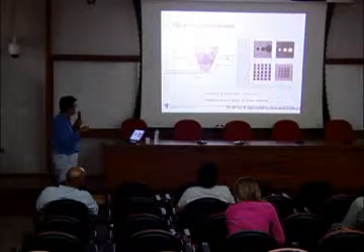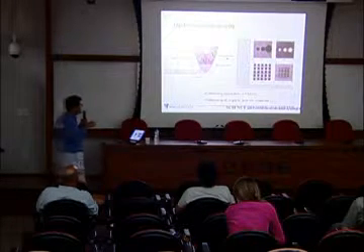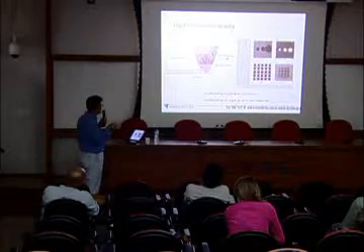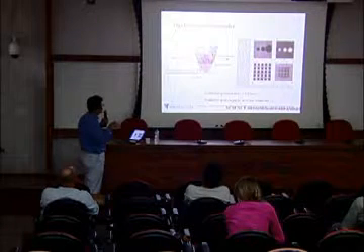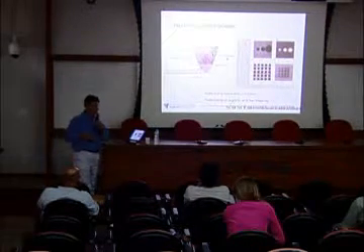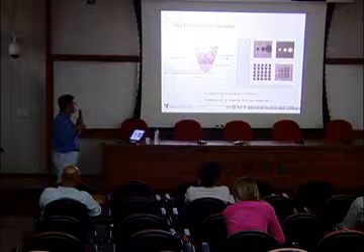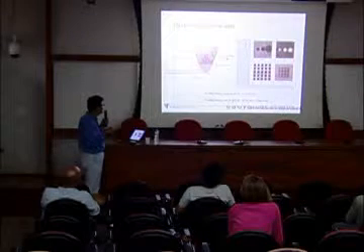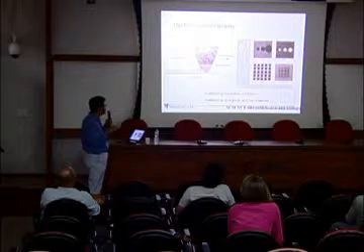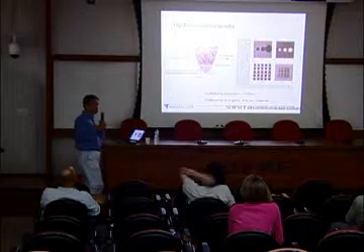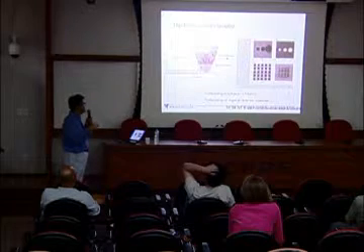The small moisture, when this tip is approaching the surface, small moisture will be attracted by the capillary action between this AFM tip and the surface. Then that will form a meniscus. Okay? Then, due to this capillary action, the liquid will be formed. Then that will increase the friction on the tip. So that's why he sees some stiction of the tip on the surface.